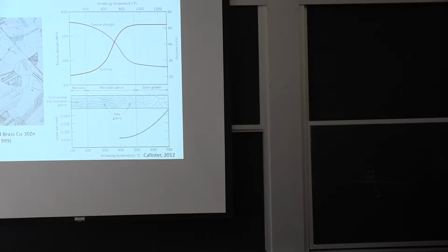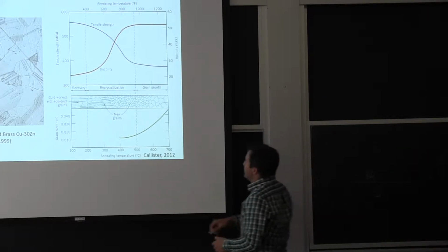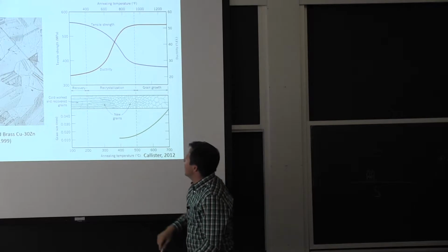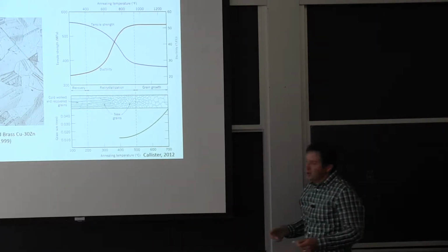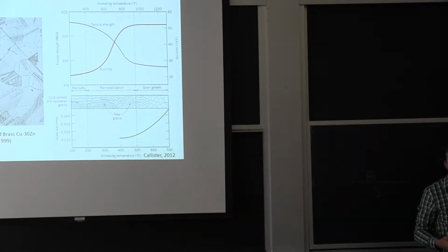Typically though, you try to do it almost at constant temperature and wait. If your desire is just to recrystallize, there's a certain range for an alloy. It's not as complicated as it may seem. You just get to a certain temperature, and then you wait an hour or less, and you're done, essentially. Those copper pieces we were looking at were 1 hour in the oven.